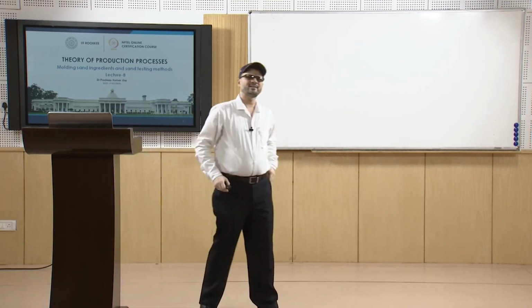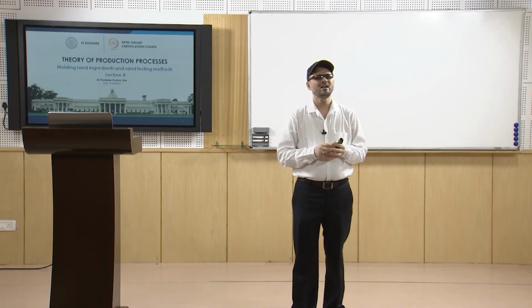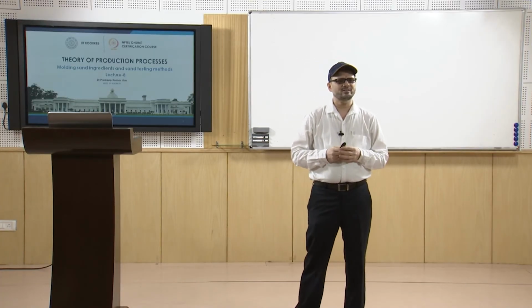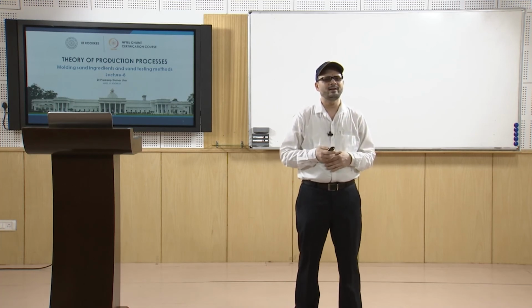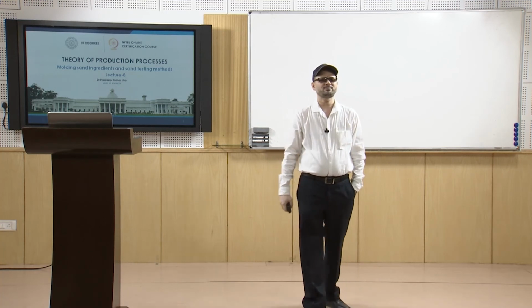Then you have the clay content test. Clay is basically defined as that particular particle which is failing to settle at a certain rate. So, that is how clay is defined. It fails to settle 1 inch per minute when suspended in water.